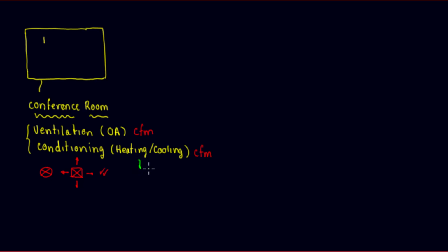So you can do this in Trace 3D or Carrier Hub, or there are other different softwares. And then ventilation, you can just do this depending on the location. In this case, very common to use IMC 2015 or whichever is applicable to the jurisdiction. All right. So for this example, we're going to take the ventilation outside air, and then we're going to make a quick example, and then we're going to select the size.